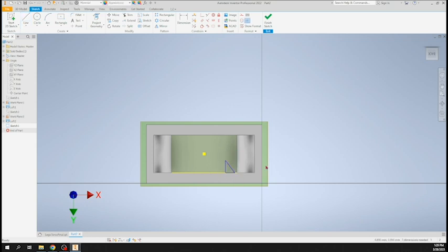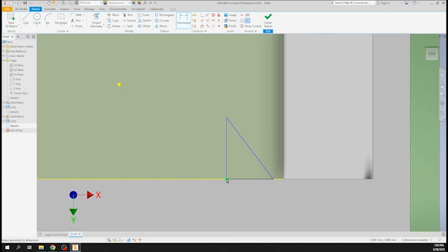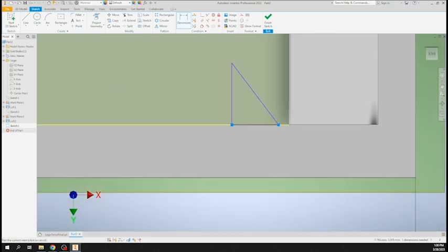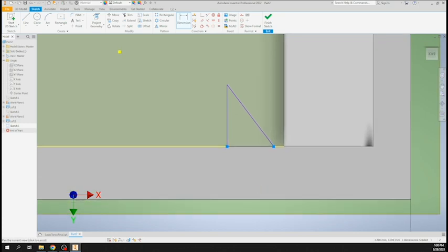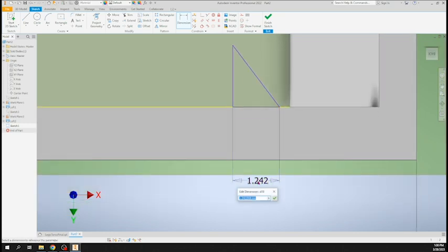All right. Now, what you're going to do is use the dimension tool at the top, dimensions. First we're going to measure from this point to here, and this should be 0.8. So what you can do is move the dimension off, click it one time, and then you have the option to enter 0.8.